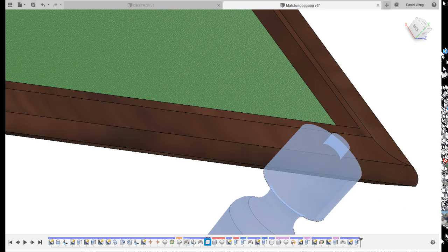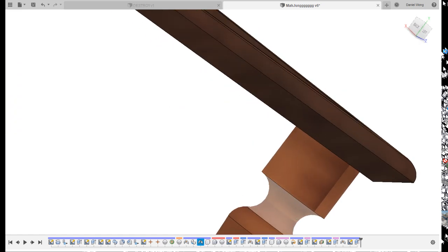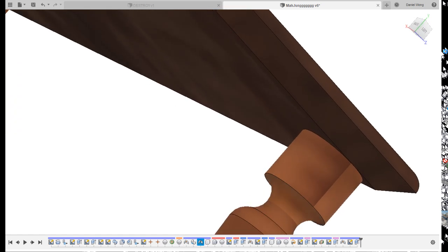And this particular pin here, I'm not sure if I can show it. I think I can. It's a rigid joint there. This one here, edit joint. I can change that to a revolute joint, which means that it can actually spin in place. Okay? Because it's on a cylinder pin, a little cylindrical pin, and so it can actually spin in place. And again, that's still 1 degree of freedom. It has to stick in there, but it's allowed to spin in place. Right? So that's rotation, and that's 1 degree of freedom.